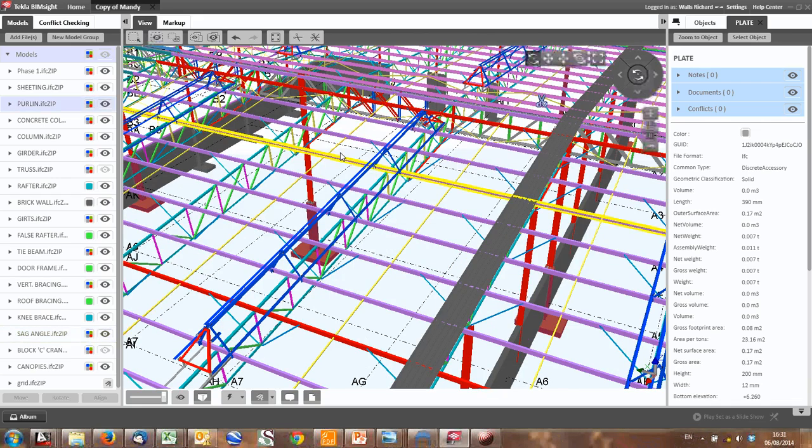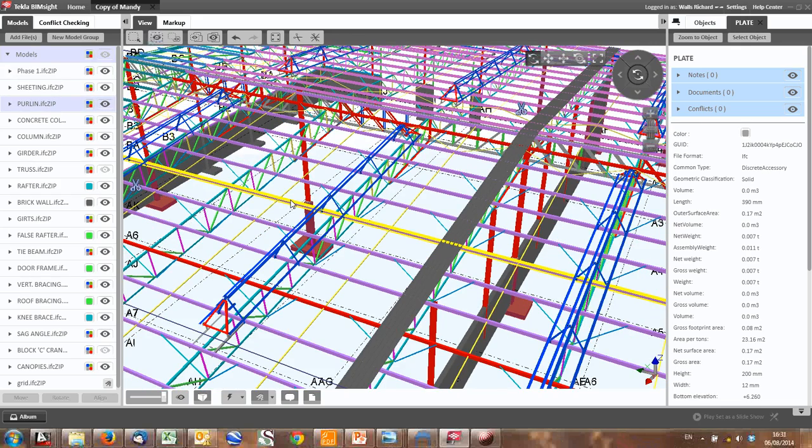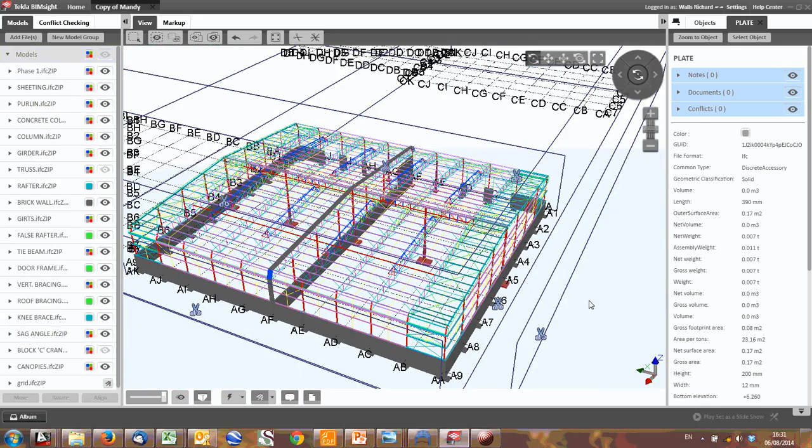You need to think to yourself, where do those loads go? Or if there's lots of ducting hanging from these wheels, how do those loads get to the foundation? When the wind blows on this side of the building, how do those loads get supported? If you don't know where the loads are going, you have a very big problem. That may mean your structure is not stable.